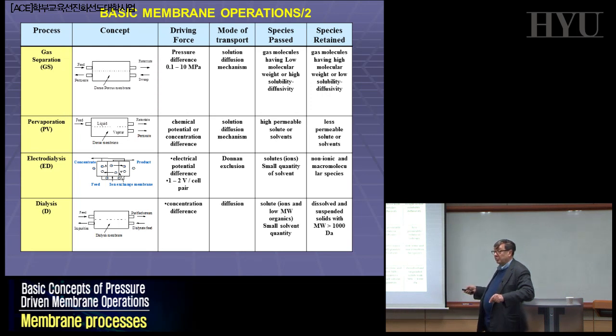Another interesting problem that we will discuss is pervaporation. Pervaporation is very similar in first approximation to gas diffusion, but it is different. Here you are looking for materials in which one solvent, water, can be easily dissolved, and another one, ethanol, does not dissolve. Or you can have some species, paraform, orthoform of the same hydrocarbons, the paracresol, metacresol, or something similar. And there are species in which the solubility of the two species is different in some polymers. If you do this, you can realize the pervaporation.